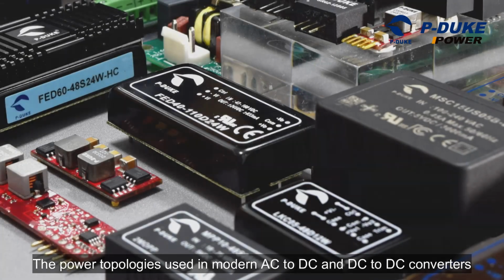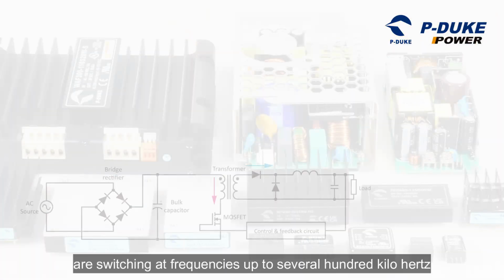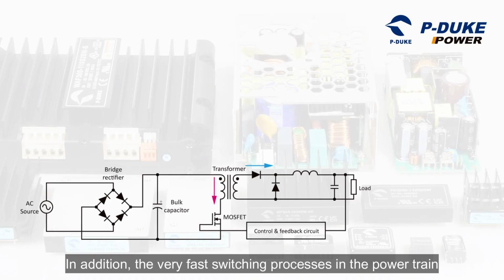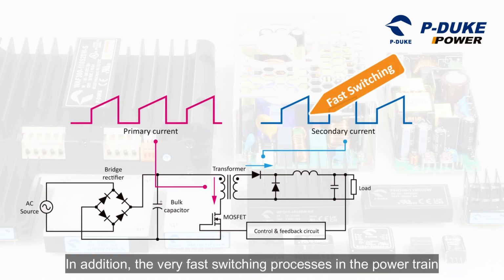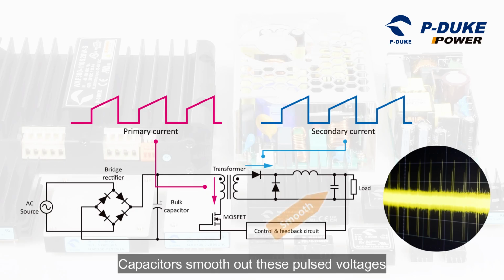The power topologies used in modern AC to DC and DC to DC converters are switching at frequencies up to several hundred kHz. In addition, the very fast switching processes in the powertrain generate high-frequency spikes on the output voltage. Capacitors smooth out these pulsed voltages.